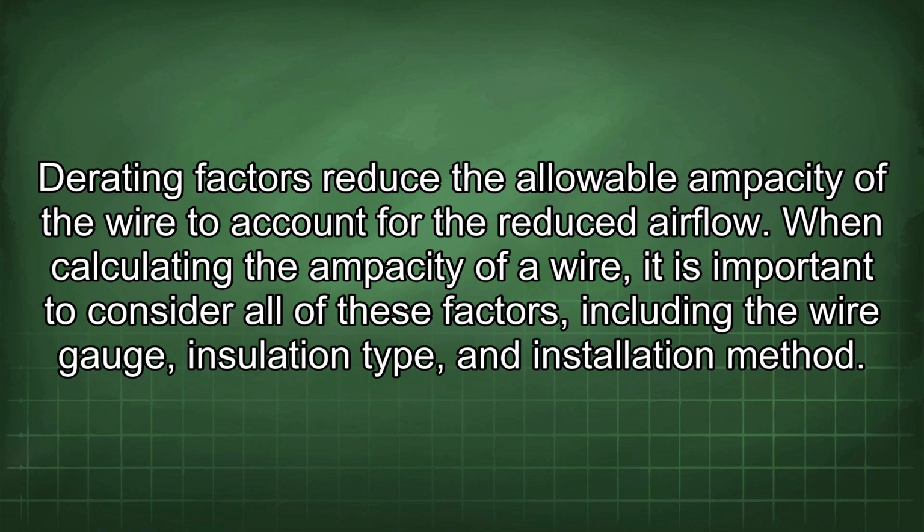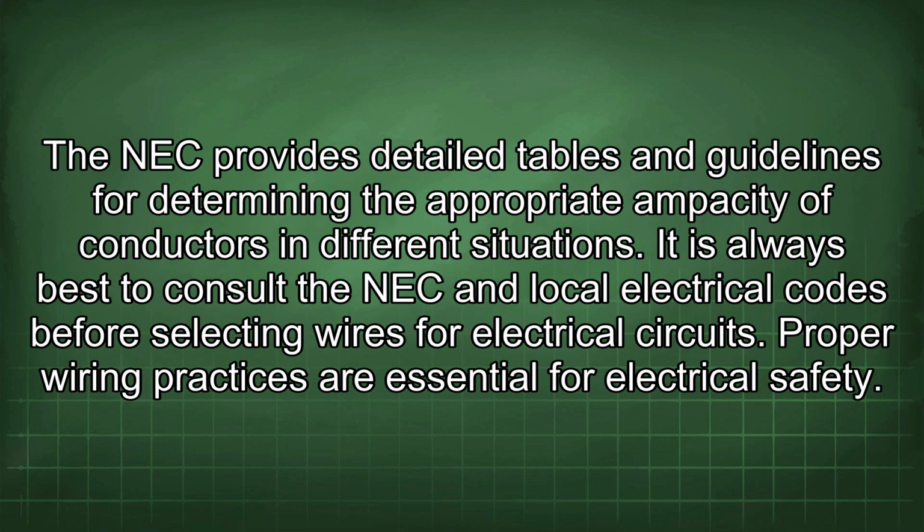When calculating the ampacity of a wire, it is important to consider all of these factors, including the wire gauge, insulation type, and installation method. The NEC provides detailed tables and guidelines for determining the appropriate ampacity of conductors in different situations. It is always best to consult the NEC and local electrical codes before selecting wires for electrical circuits. Proper wiring practices are essential for electrical safety.